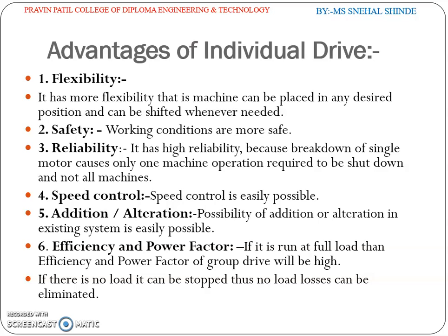Now, advantages of the individual drive. Flexibility, it has more flexibility. That is, a machine can be placed in any desired position and can be shifted whenever needed. Safety, working conditions are more safe. Reliability, it has higher reliability because a breakdown of a single motor causes only one machine operation to be shut down and not all the machines.